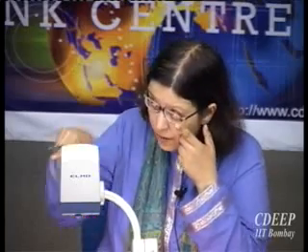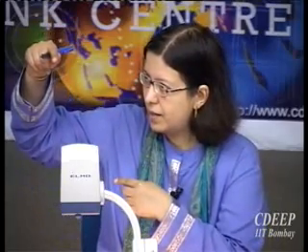And your frequency range also depends on the design specification. You want to design a VCO with a range of 1 gigahertz to 2 gigahertz. Practically, you may want to design it from 0 to 2 gigahertz. But suppose this is the range given to you, 1 gigahertz to 2 gigahertz. That also affects your KVCO, right? Because it's a current starved inverter, your KVCO is a function of that current source that you are putting there.